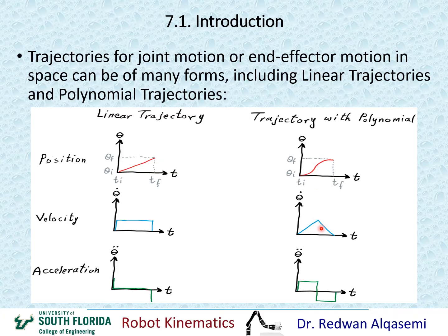So that slope basically switches back down into the slope that we see here. Now, since this velocity profile has a constant slope for this curve, that means we also have constant acceleration for this particular period. Again, we're going here from this velocity to whatever maximum velocity, but we're doing this in time. So we don't have that infinite acceleration, but we're suddenly going from acceleration 0 to whatever value here, and then switching down the acceleration to deceleration at the midpoint,